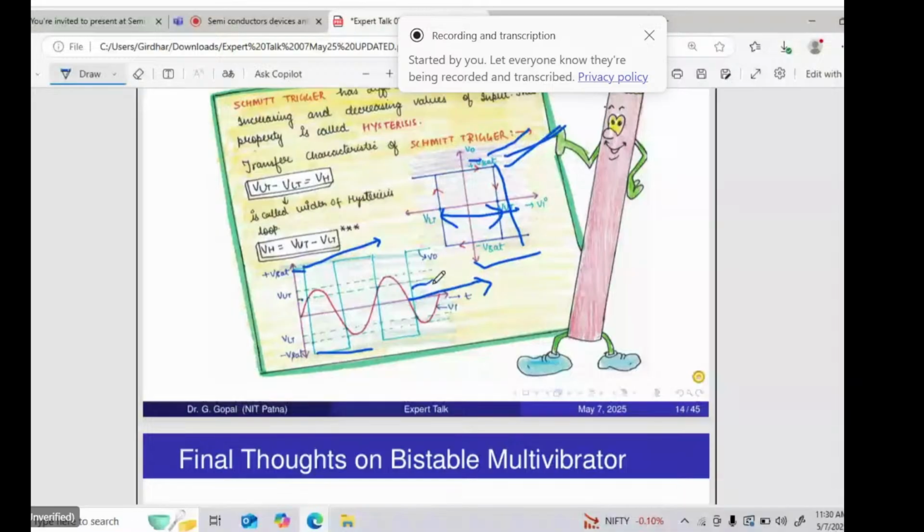When you consider V0 only, you are considering only one source voltage V0, and VR is connected to ground. V1 is the voltage across R1, so V1 is V0 times R1 divided by R1 plus R2. Now if you consider VR only, and the V0 node is connected to ground, V1 is now the voltage across R2. So V1 is VR, the source voltage, multiplied by R2 divided by R1 plus R2.